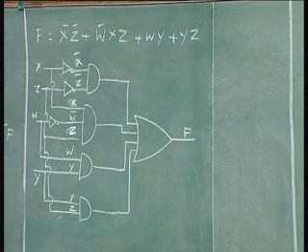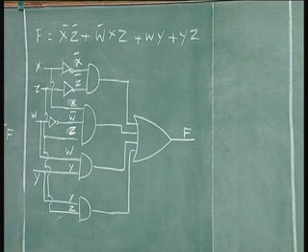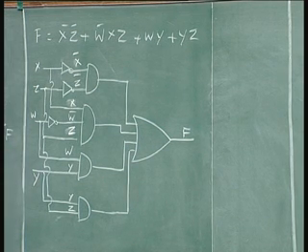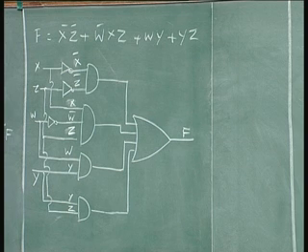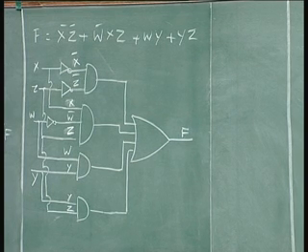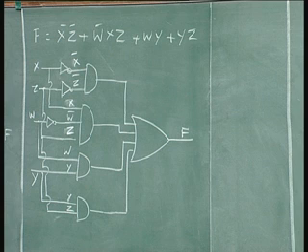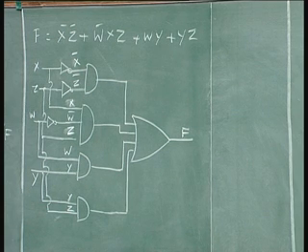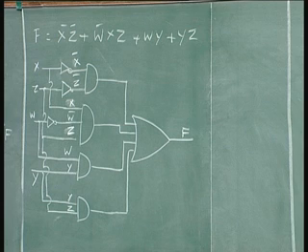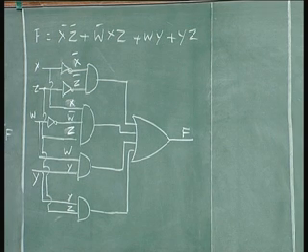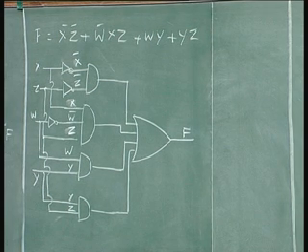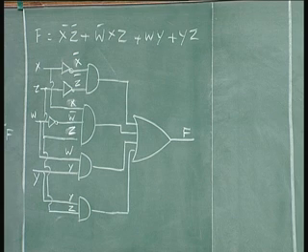This is the function which we are trying to represent, by this circuit whose Karnaugh map is this and whose functional description is this. Of course, I can already write the truth table. Truth table is only an expansion of this. I will have to put the w, x, y, z, all the 4 combinations 0, 0, 0, 0 to 1, 1, 1, 1, and then put here finally 1 and 0.